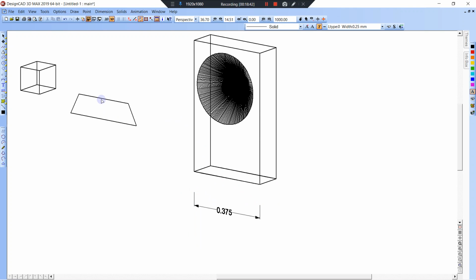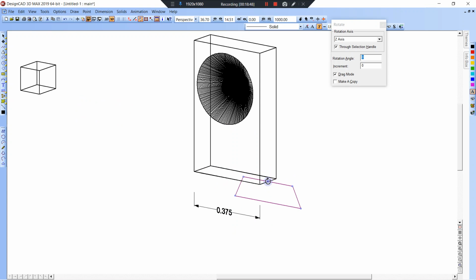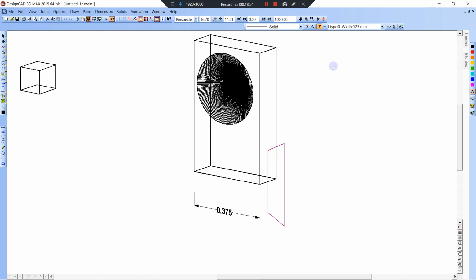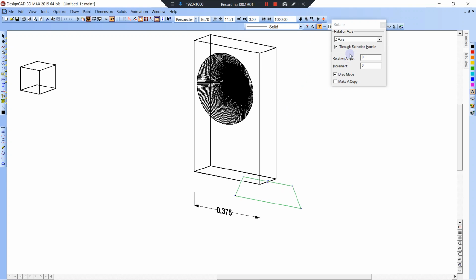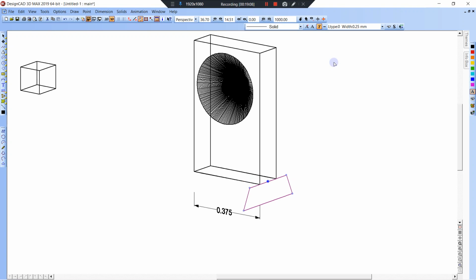And then take this, Control K. Control K. Gotta go here, Control K. Rotate R in the Z, 90 degrees. Nope, Control Z. Oh, that's R. Seems like it should be in. Oh no, no Y. Axis 90 degrees. Okay. So now this is going to slide in. Now it's facing in the correct position, and let me measure this.